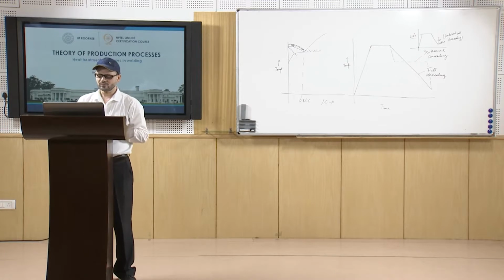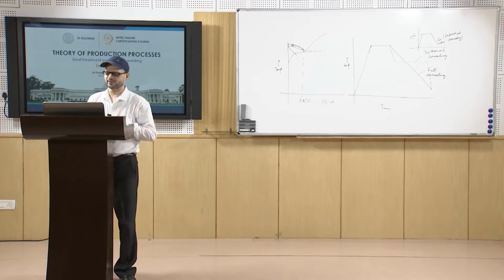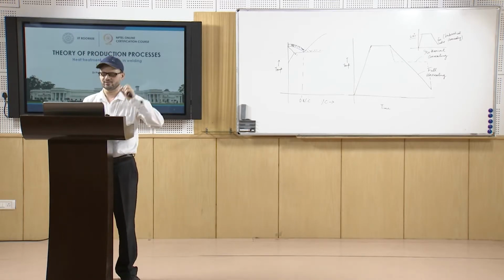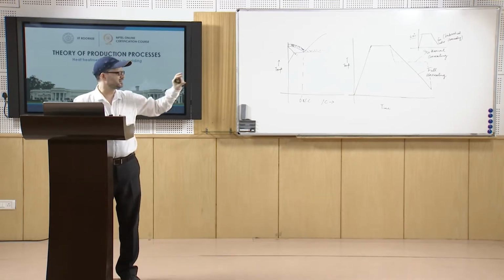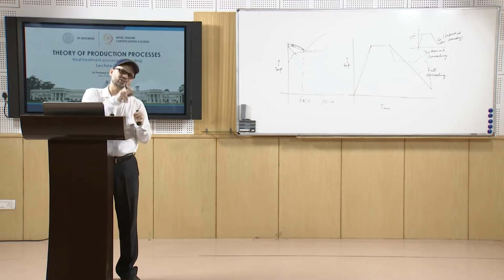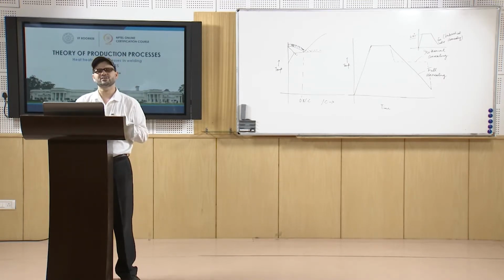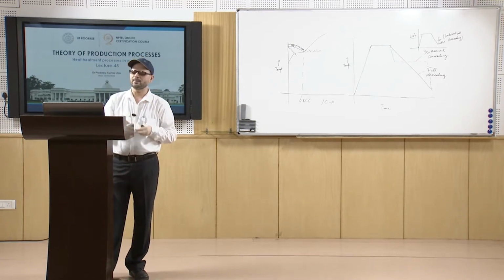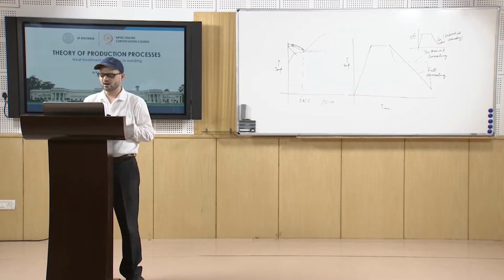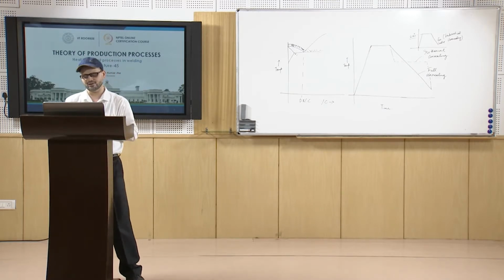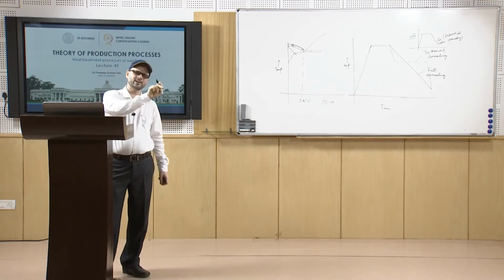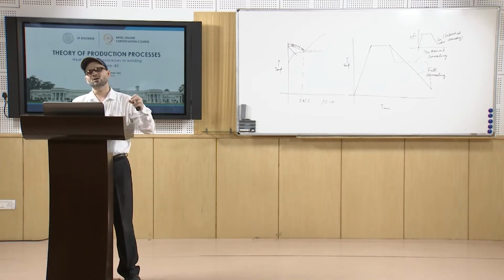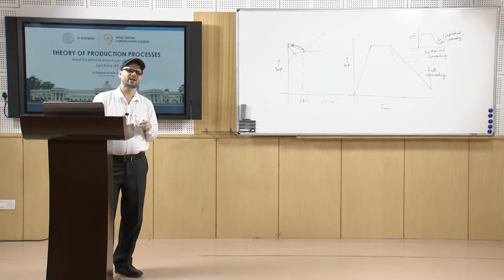The treatment we give in this case is that we heat to just above the lower critical temperature, about 700 or 720 degrees centigrade, then we hold for some time, and further we come down and hold it at a lower temperature for some time again, and then we go for a different type of cooling mechanism.